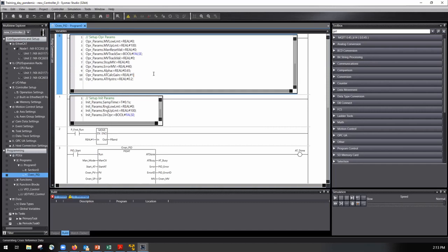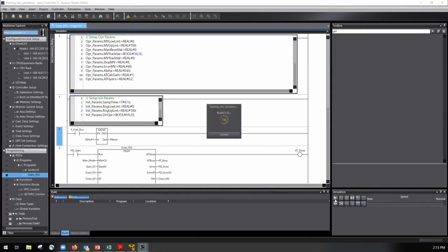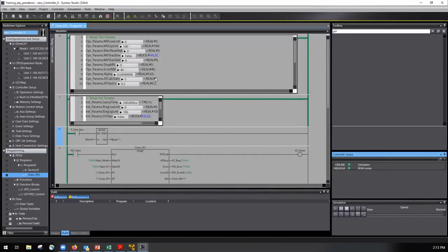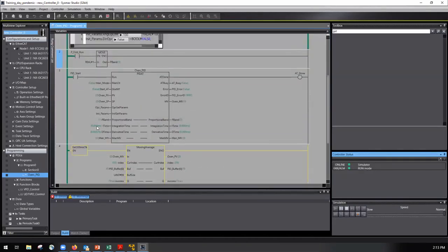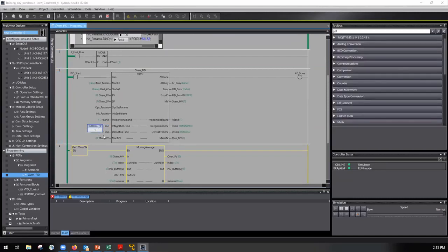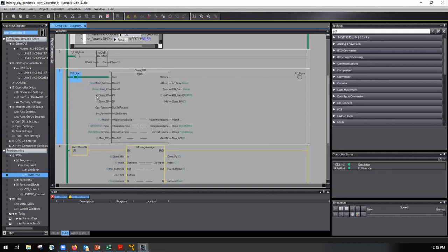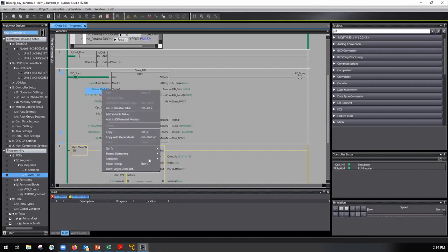So I'm going to make that 1, and I'm going to rerun this simulation. And it's probably going to be too reactive to even auto-tune. So I change that to 1 now, making it super jumpy. I'm just going to give some starting values here. Turn on. Give a set point of 50, we'll say. Now I'll try my auto tune with that new parameter in there.